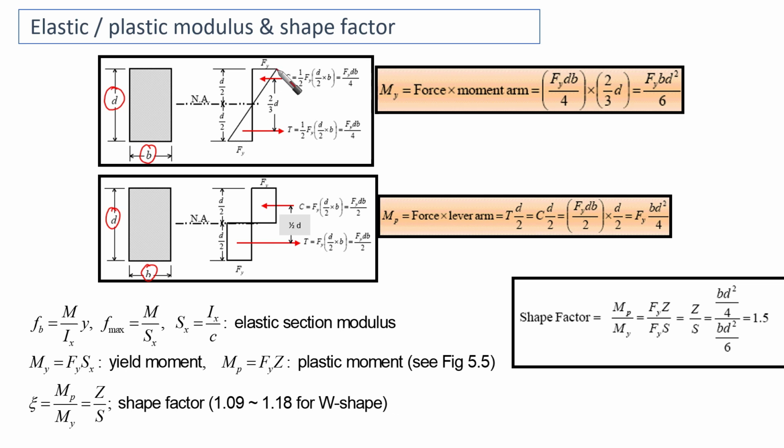Starting from the beginning, you're going to find, first of all, the neutral axis, as we said, whether for elastic or plastic sections, it is going to be in the middle. Here, because we have a triangle, the centroid of the upper half for the forces is going to be, we call it C. This C is going to be the area of this triangle multiplied by the width, right?